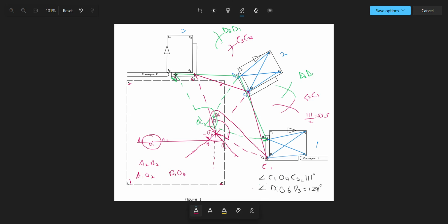And if it's going to pass over O6, you have to bend O4 to C1 so that it does not pass over it. Because if it passes over it, the mechanism cannot complete the toggle position. It cannot complete that 111 degrees, because there's a pivot here.